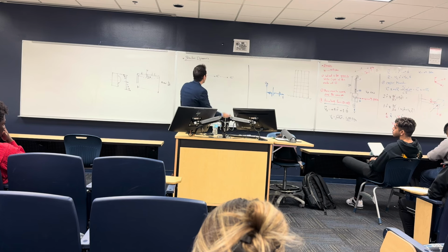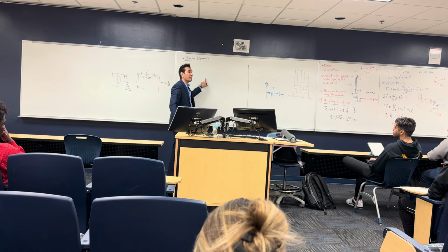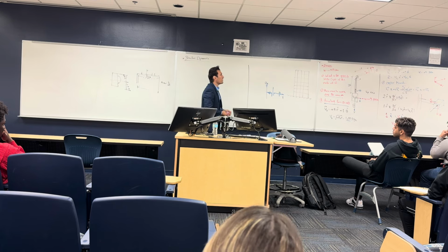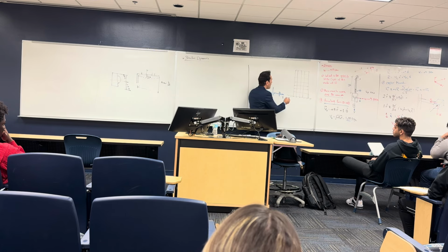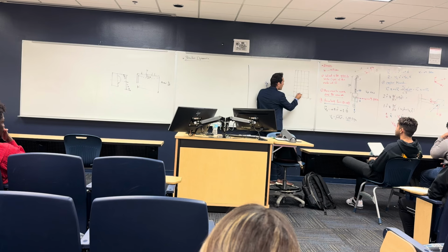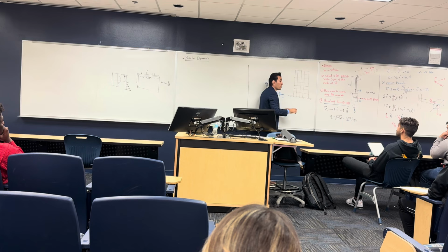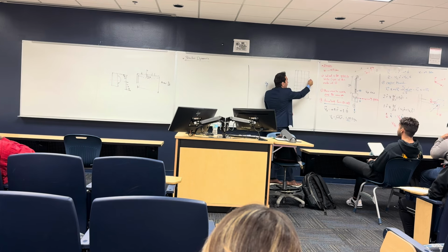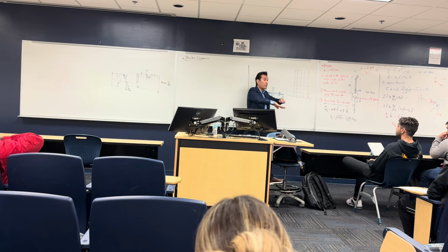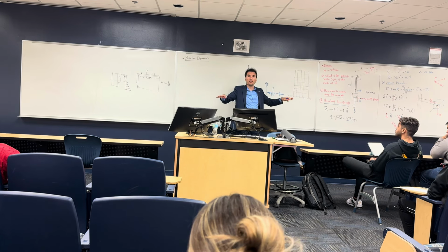But the thing is, solving an earthquake problem for a building like this is very, very hard. Why? Because as I told you, we engineers are interested in delta, okay? But this building has lots of degrees of freedom. I want to know the delta here, the delta here, the delta at all the structure points. The structure has multiple degrees of freedom. This point is moving differently from this point, which is moving differently from this point, and it's 3D, so it's a very, very difficult problem.